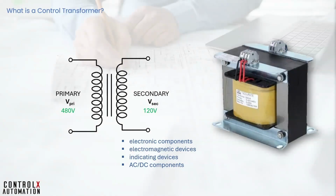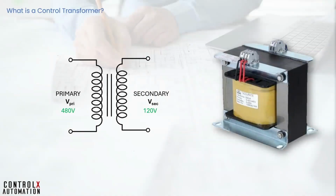You may ask, why not just use a general purpose transformer? What's so special about a control transformer? You see, control transformers are not the same as general purpose transformers. They are specifically designed to handle the high inrush current produced when multiple inductive loads like contactor coils and solenoid valves energize simultaneously. A general purpose transformer would exhibit excessive secondary voltage sag under these inrush conditions, causing coils to drop out or fail to pull in.